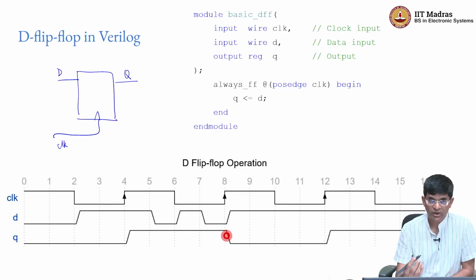Now, some of you hopefully are already thinking this through and saying, hey, these are real wires with real delays, capacitance and so on. At least that's what I've been talking about so far. Isn't there a chance that this clock edge comes slightly delayed? How do I know that I'm not going to see it over here, or even worse, somewhere during this transition period? What happens if something like that happens? Yes, it's entirely a possibility, and in order to make sure such things don't happen, we need to have constraints on timing, which we will get to later.